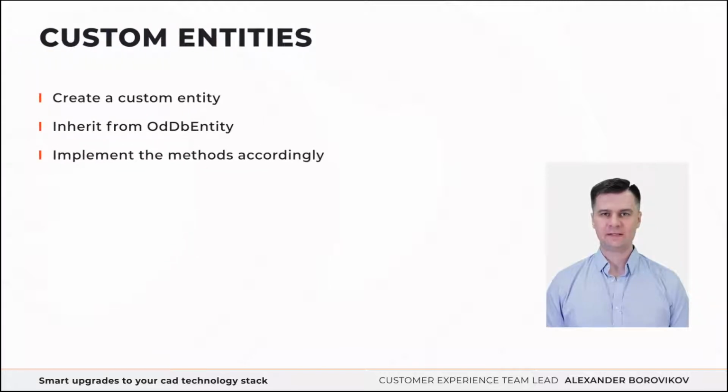The application specifics may require a custom entity being introduced and added together with the standard CAD elements. In this case, you can create a custom entity inherited from ODDB entity and implement all the necessary methods accordingly. Among those, you will implement the draw methods that will define the look of the entity being visualized. Such an entity with a custom draw implementation will be processed similar to other ODDB entity inherited entities.